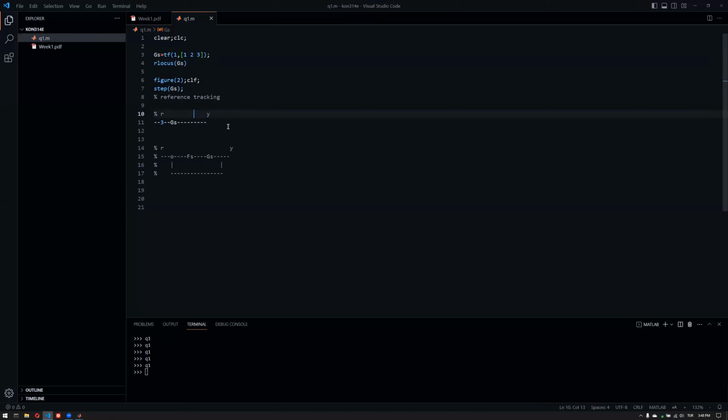So, for example, if you have a vehicle and you have modeled your vehicle dynamics with this transfer function here, you're just pressing the gas pedal to a certain degree, exactly 3 times the unit step. So it's going to be a certain angle here. And you're assuming that your car will reach a certain speed. Now, if you're going downhill or uphill, you're not looking at the output value. So you're not measuring your velocity. You don't know if you're faster than you expected or even slower than you expected.